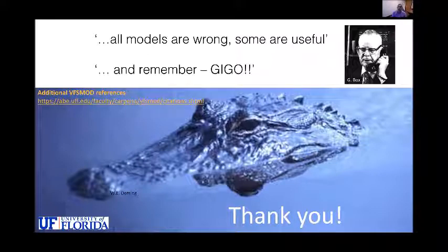And now, what we can do from event to event is just follow this time series of water table as described by, that is a good question, described by what? So we go back to the schemes that we are putting together. I'm working right now with the SWAN tool in the European Union for higher tier, step 4 tier assessments. And we can use the water table that is incorporated in the aquatic model, in the mass balance that they do, the fluctuation of that, in this case TOXWA. In the EPA it would be BVWM. So we have a reference there, and then we make assumptions on how deep the canal is with respect to the surface, and then we just watch the variation.